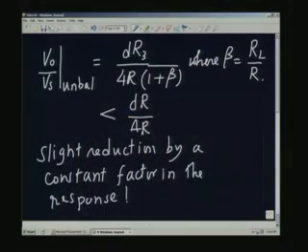So, the lead wire compensation, by having a 3-wire arrangement for the gauge, does the following two things. One, it does not change the null condition under the balance condition when there is no strain in the strain gauge, and secondly, it reduces by a constant factor the output when the strain gauge has undergone a change in its length. Okay. So, this is a very important thing to know, and let us just take a simple example,